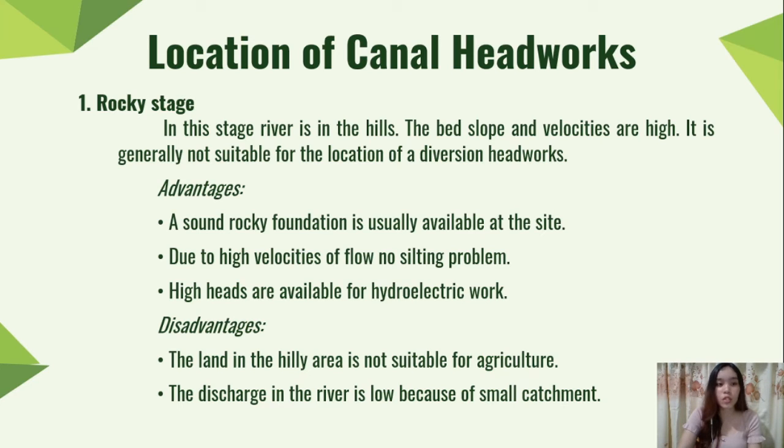So the first location is the rocky stage. In this stage, the river is in hills, the bed slope and velocities are high, and it is generally not suitable for the location of a diversion headworks. And it has advantages and disadvantages. So let us first discuss the advantages.